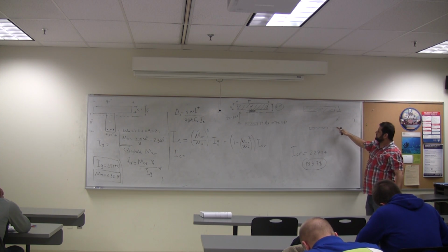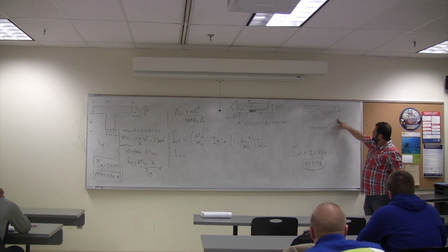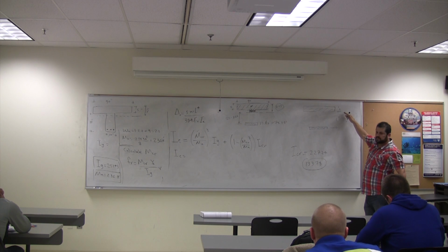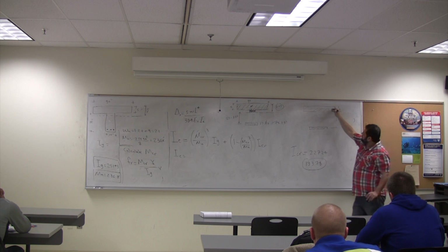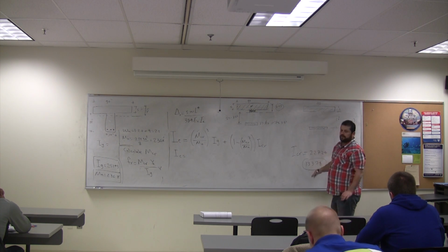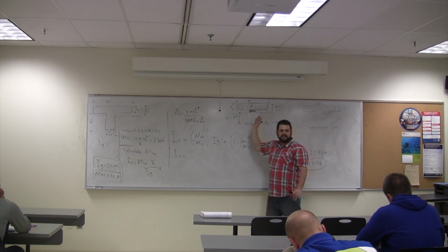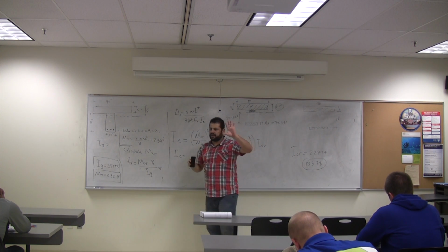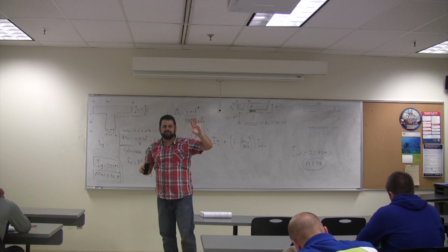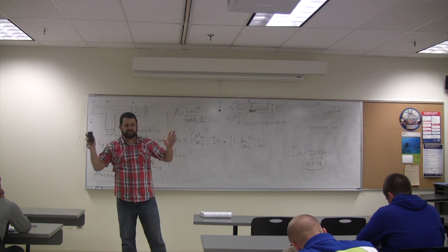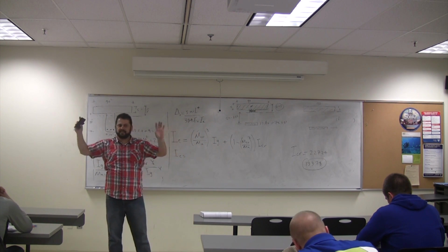It's not 19, it's 17, right? 22 minus 5 is 17, right? To here. And this is 9. You know why? Again, I'm explaining. When I check KD, that K is based on rectangular analysis. If it's more than HF, the thickness of the flange, it cannot be because we are assuming there is area that doesn't exist.